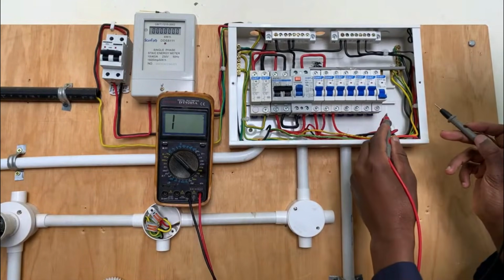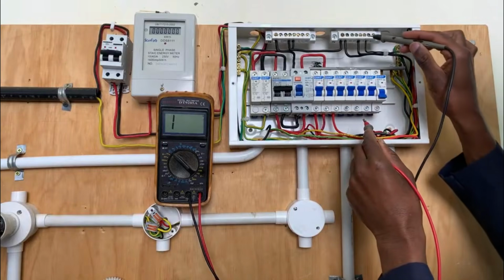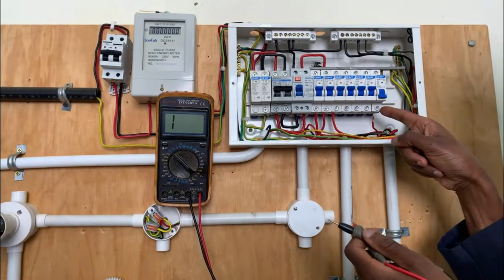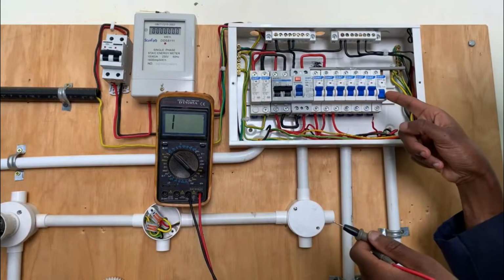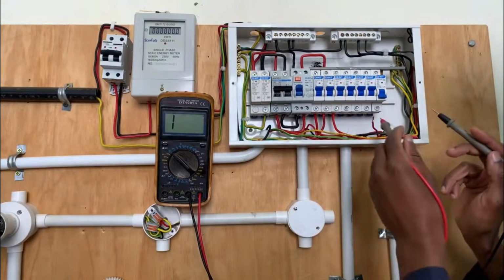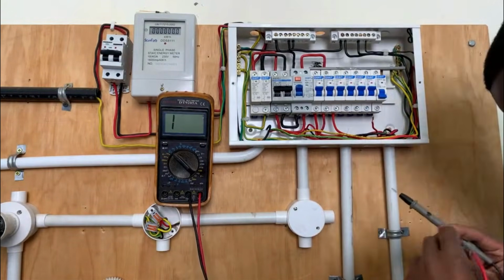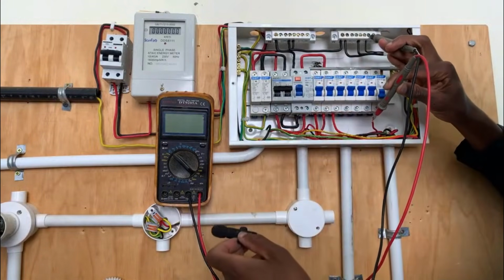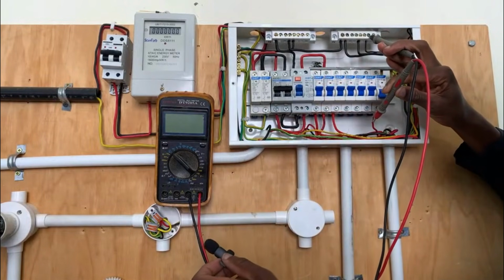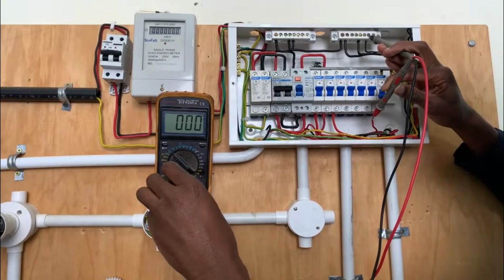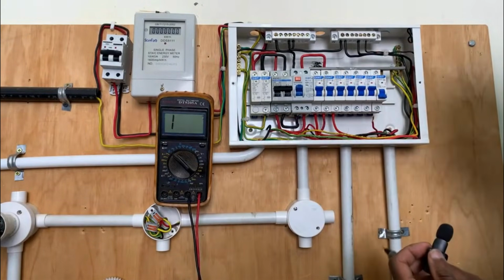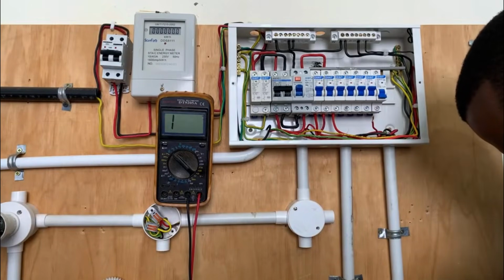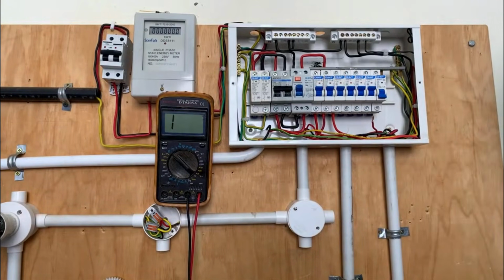What happens if we get it? Now we place the probe there, and on the neutral bar there is a problem. It means that if we reconnect it back and we switch the MCB on, it will still trip because the line and the neutral are short circuiting. If you place one probe on the neutral and the other probe on the line that is serving that specific circuit, there's an issue. You hear the sound? Now we have to get rid of that problem, and that is our assignment for today. Get rid of the problem so that you can be able to fix it.